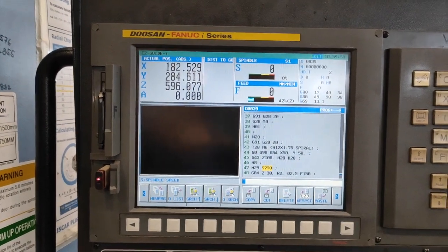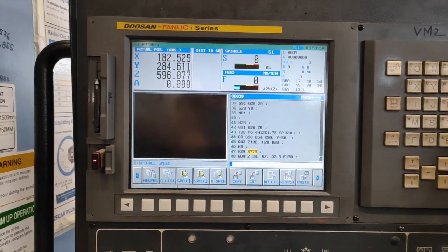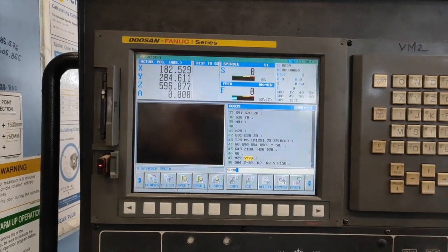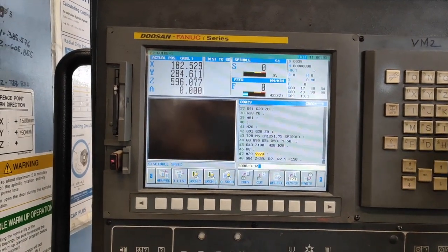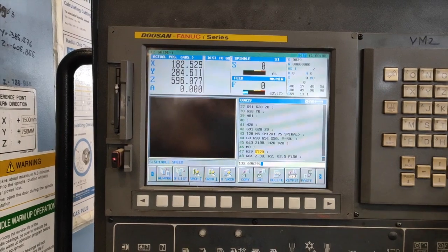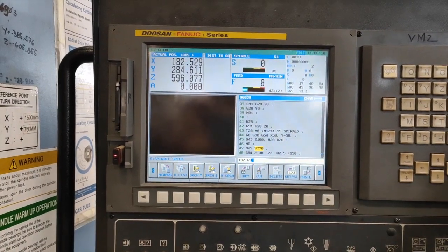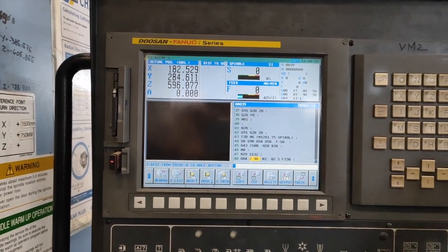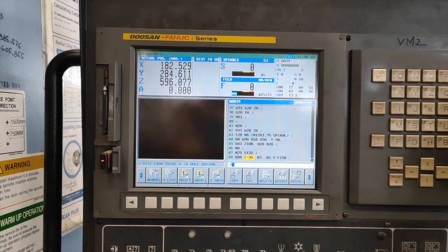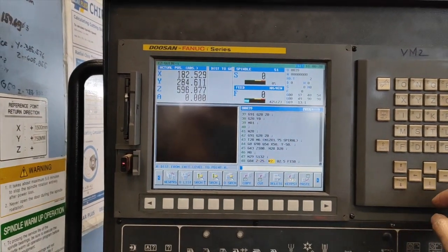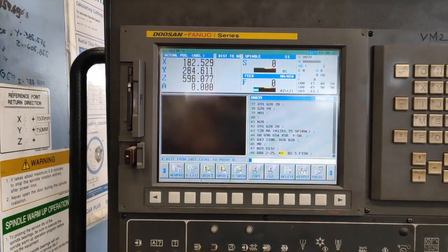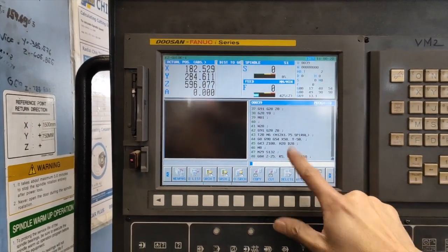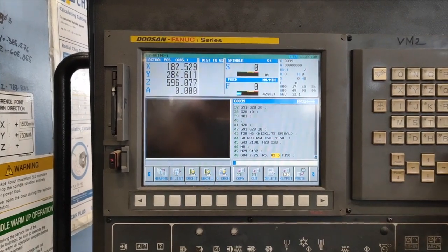And I'm going to compute my spindle speed. Let's say 5 meters per minute times 1000. So it's 5,000 divided by 3.14 divided by 12. So that's my spindle speed, 132. And I will change my depth. Make this one minus 25. And also I will alter my retract to 5 mil. And I'm going to remove the Q.